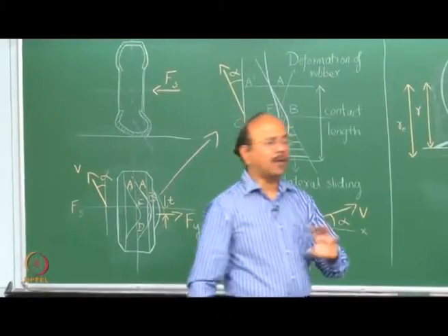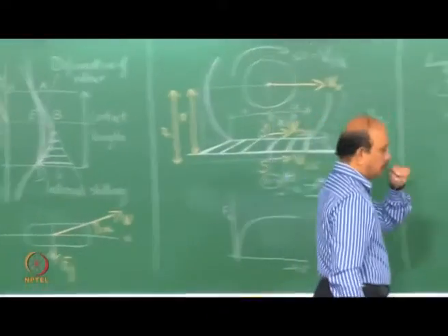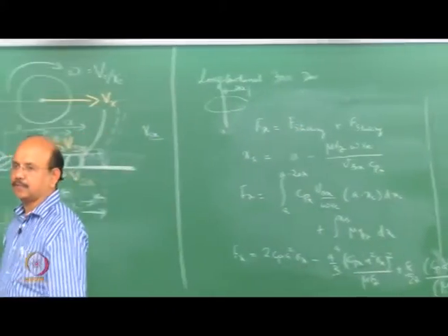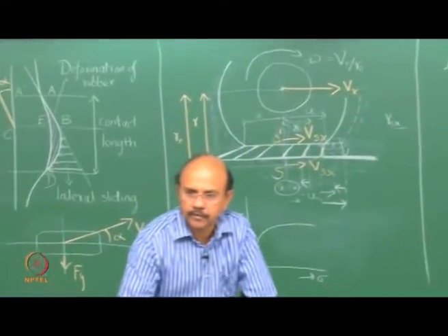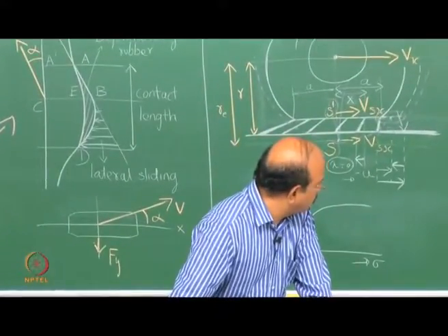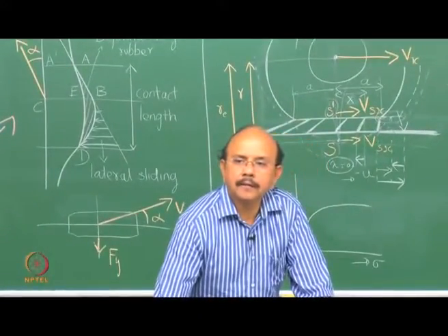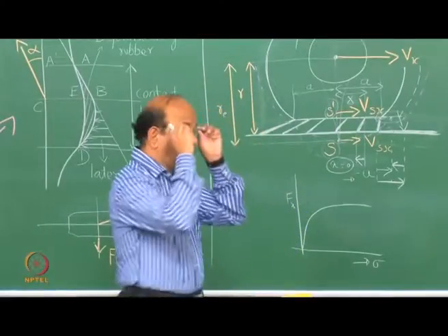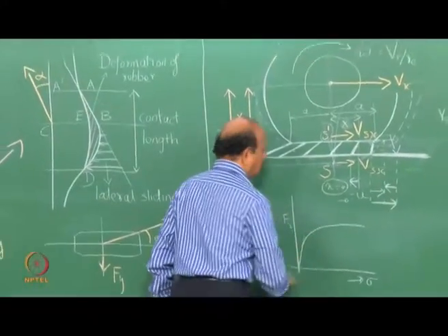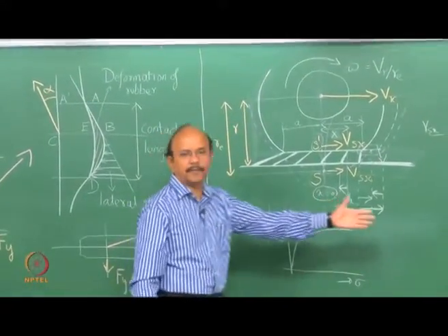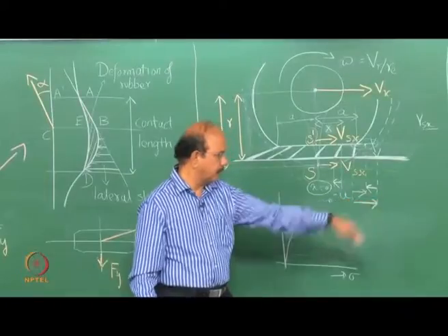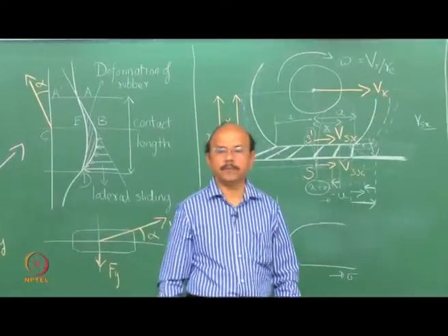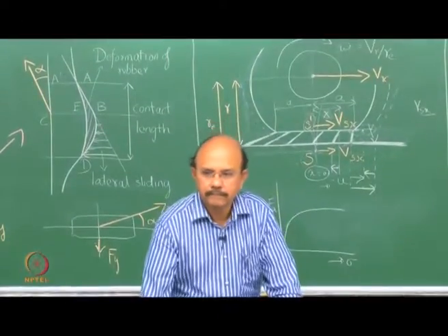For very small slip, sigma you can assume it to be equal to kappa. The first term gets into picture. Okay. So one of the quantities of interest to us, you will see that later, is always the slope here, which can be approximated, if you look at kappa, to be 2cp a squared.